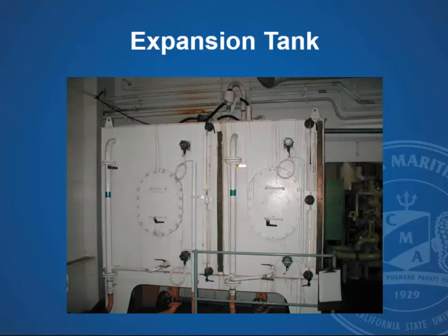They're there to give a pressure head to the suction of the pump. They also serve as, the name gives you, an expansion tank. As the system cools down or heats up, the water in the tank will expand or contract. Usually you keep the expansion tanks about 3/4 full.